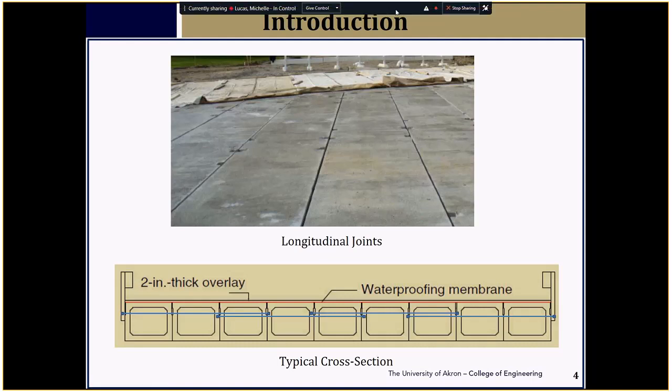Snug tight tie rods will probably give us about 15 kips of force for each tie rod. The maximum spacing of these tie rods along the length of the box beams is 25 feet, and it's the practice to provide tie rods at that maximum spacing.